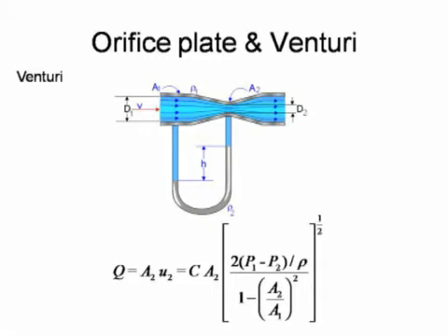On the right hand side of the equation, apart from the rearrangement, we've also added a discharge coefficient, illustrated here as being capital C, sometimes CD. And that really is something to take into account some of the energy losses in our system. So for an orifice plate that might be 0.6, 0.7, whereas in a venturi maybe 0.9, 0.96, something of that sort of order.